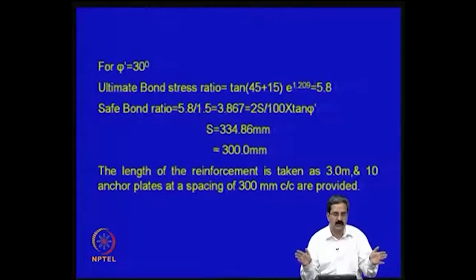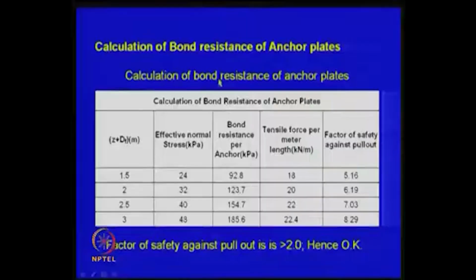Now, I will just take B equal to 1.5, and the total length is 3 meters only. You should also have seen that x naught, right. x naught is a part of the total length L naught; L naught minus x naught will give you the pull out resistance, and x naught is the length at the location of maximum shear stress. So, with this spacing one can go ahead, and if you want to calculate how it looks, you can see that. Is it okay?